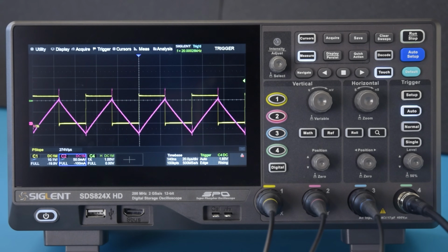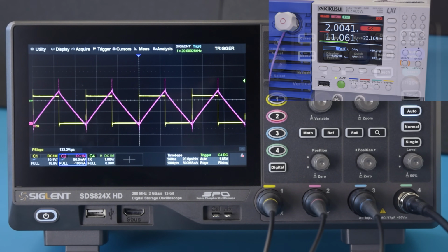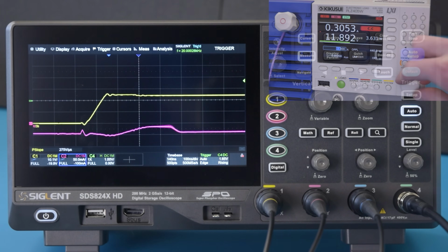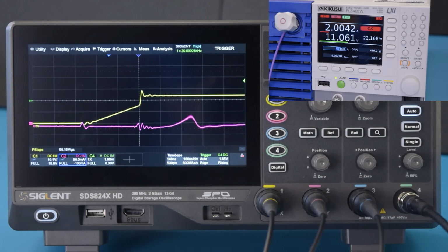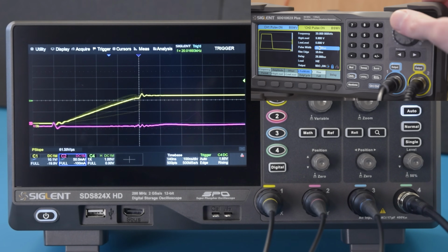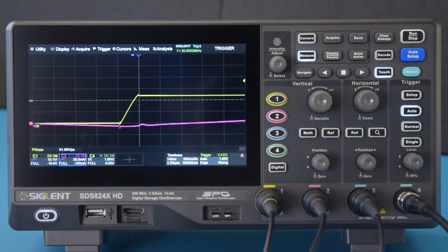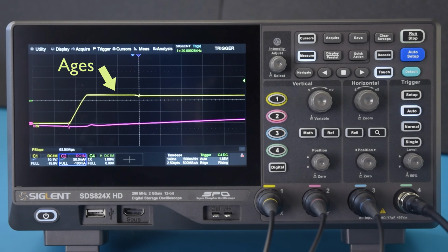In the case of this buck converter, if the load increases, shifting the current ripple up and reducing the negative portion, the voltage swing slows down. If the current is too low, the voltage won't reach zero before the switch turns on and it'll hard switch, so the dead time needs to be long enough for this to happen. However, if the dead time is too long, current will spend ages flowing through the inefficient diode before the transistor turns on, introducing additional conduction losses that could outweigh the saved switching losses.